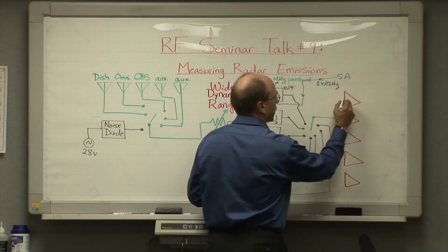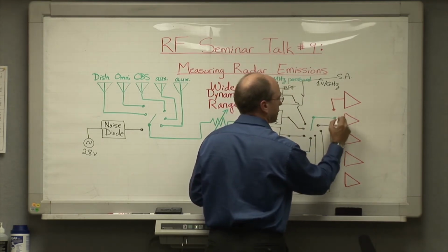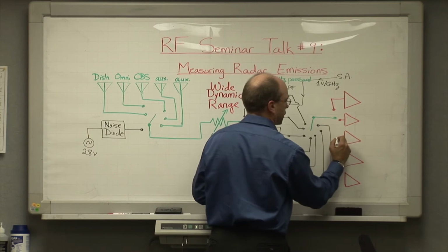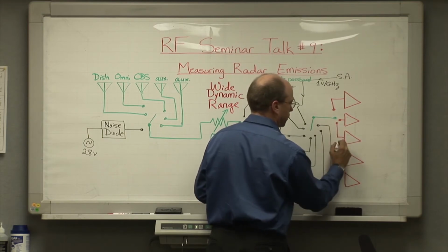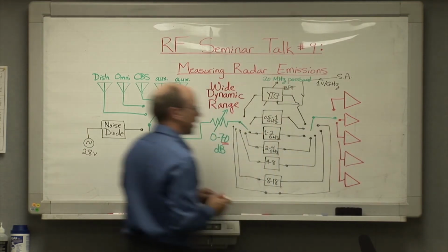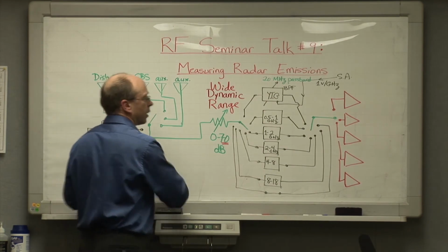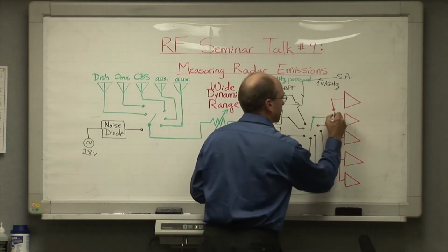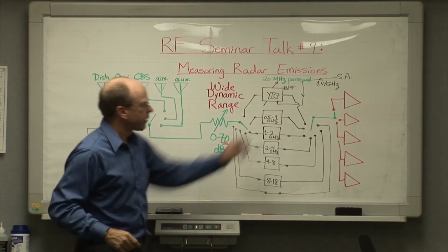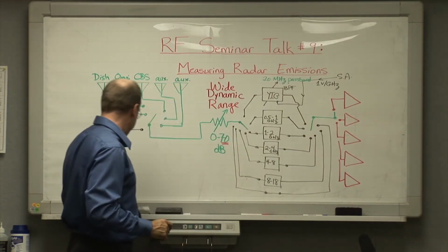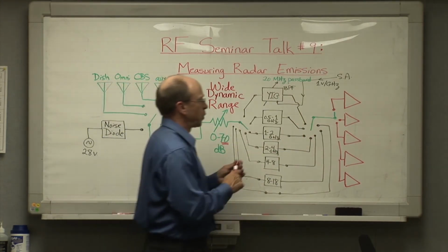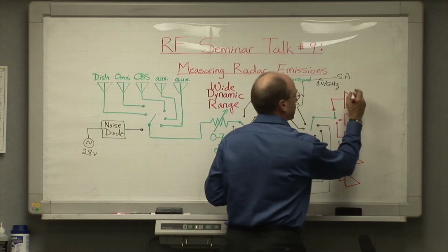Like so. And again, these low noise amplifiers can switch to, we can switch to any one of these. I'm not going to belabor it. You can see what the pattern is here. And we have a second switch here. And the reason that we have a set of these low noise amplifiers is so that, again, we can pick an amplifier which is especially well optimized.